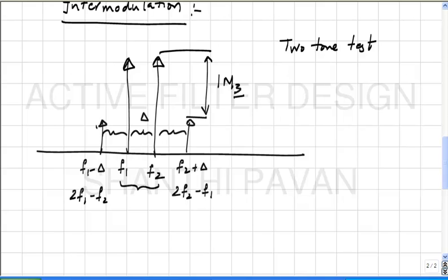Why does the distortion have to increase with input frequency? The capacitor will now carry the current. Whatever current you inject, for example in the first order filter that we saw in the very beginning of the class, some of that current is flowing through the capacitor, so this inverse stuff doesn't work quite well, because the same current is not flowing through both the transconductors.